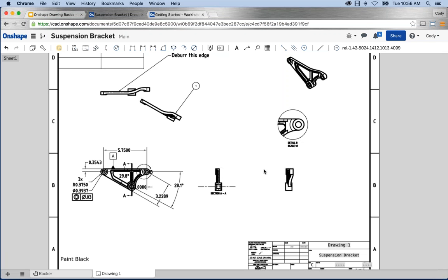The key thing to keep in mind, and this is a question from earlier as well, is do I need to import it into a certain place? Does it need to go in a very specific document? And the answer is no. You can import your DWT template, if you have that file, into any document, and Onshape will automatically recognize it.